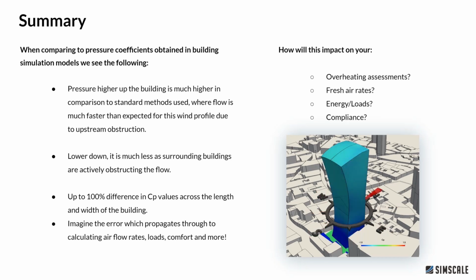And mechanical ventilation, yes, is an option. And everyone has windows, right? So we're supposed to be using natural ventilation. In the UK, we have standards like TM59, which talks more about how we can do that and how to account for window opening, ventilation, thermal comfort. But what's the point in all of that if you're not really capturing the flow properly from outside to inside? This is actually a critical thing. So this point is super important.